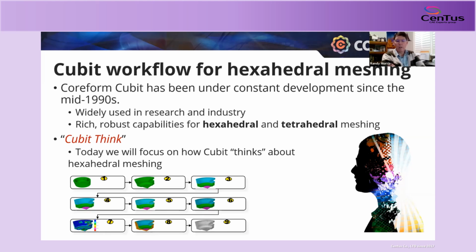We've been involved, Carl and I, with CSumSoft, and elemental technologies for almost 20 years, more than 20 years now. And Sandia's Cubit predates that. So we're going to talk about hex meshing. One of the questions is, though, what's the difference between hex meshing and tet meshing? What are the trade-offs? Cubit was developed first for hex meshing. As you might remember, the original paving algorithm was developed by Ted Blacker and Mike Stevenson back in the 90s. From that came their hex meshing algorithms.